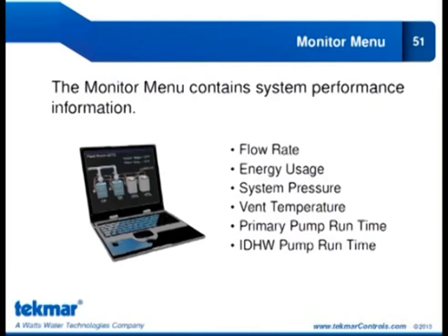I just want to touch base on the question that came in from Bill here regarding the Grundfos, from Owen. The Vortex style sensor from Grundfos. Yeah, so the idea is, again, Nick, these are available from Grundfos, but we'll probably look at carrying maybe a couple models. They do have a plastic body style, and it only goes up to about 104 gallons per minute. They do have a stainless steel version, and they call that the VFI series, and that goes up to over 400 gallons per minute. So we're looking to carry probably 2 models, and then make them available to you guys to purchase from us directly.